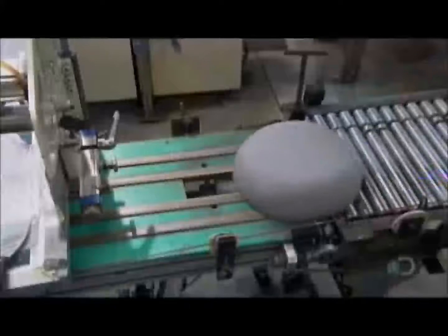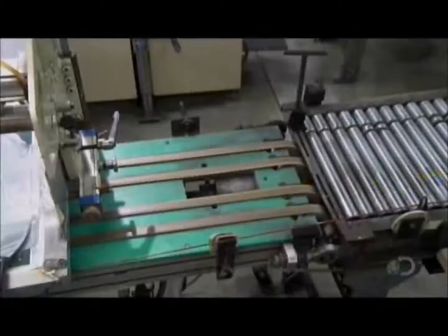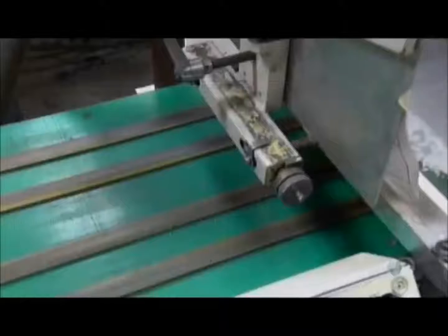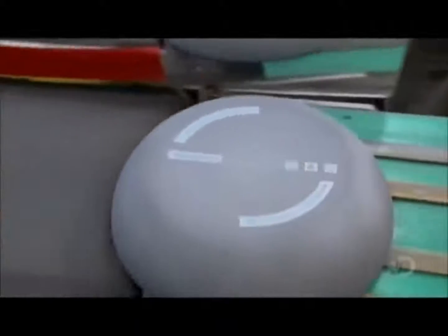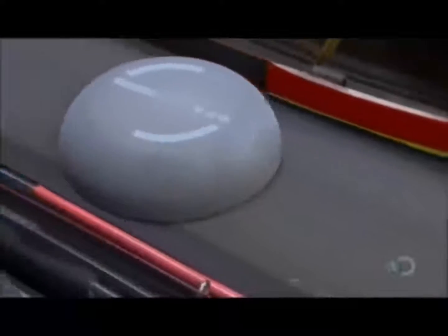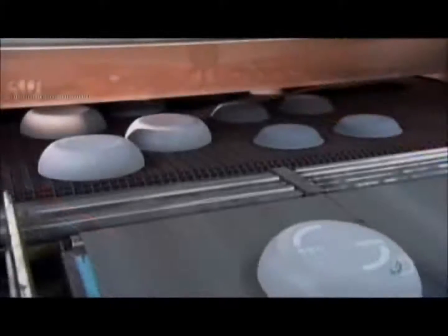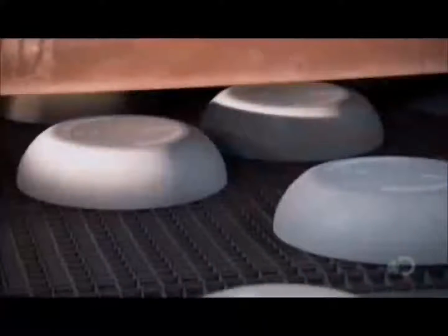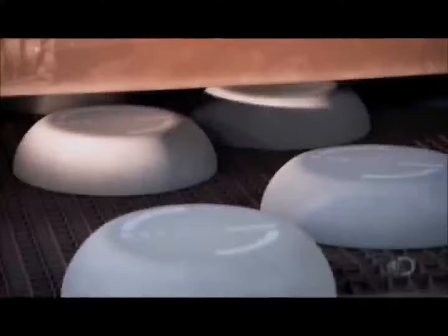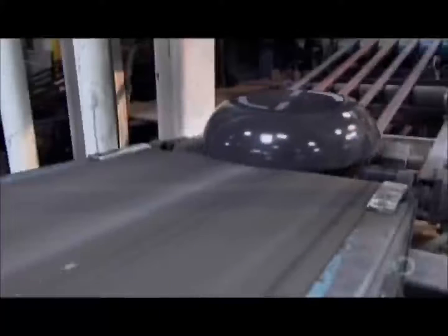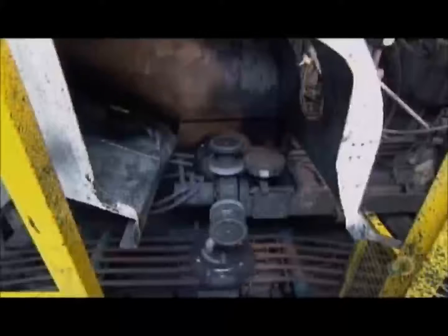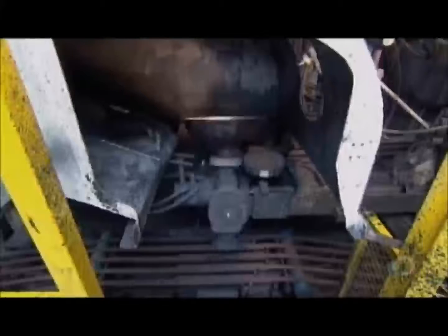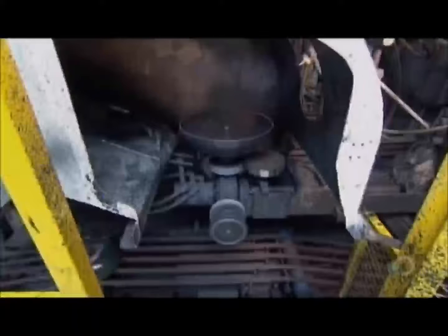After the coating, it enters a drying conveyor, where hot air pulls away the water in the enamel coating. Then the company name and other information are screened on by an automated squeegee. After that, it enters a curing oven at 560 degrees Celsius to toughen the enamel coating and deepen the color of the pan. As you can see, the color of the pan is darker.